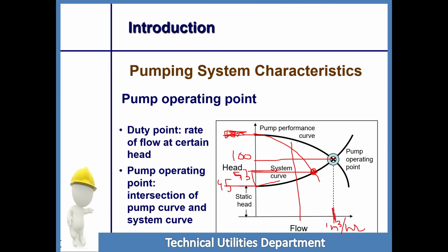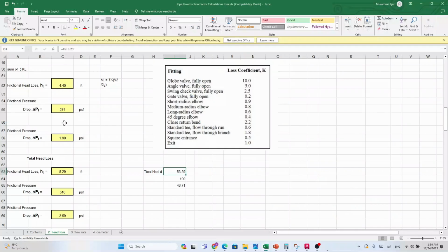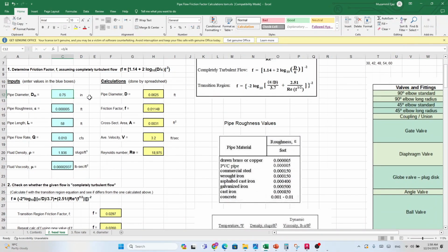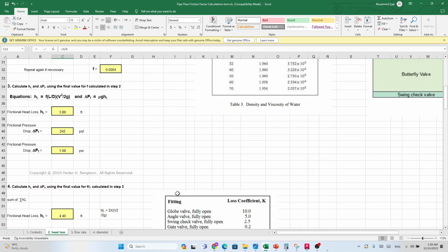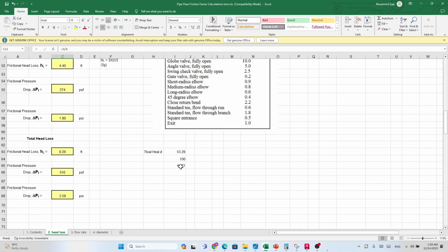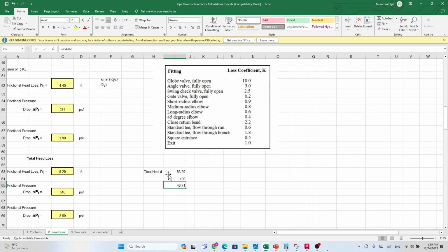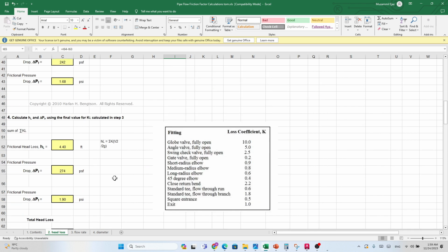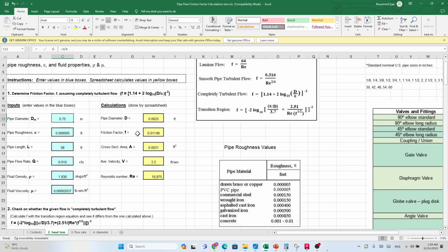So from this you can understand that you can reduce the diameter of the pipe by installing 3 upon 4. You are putting in extra installation cost. You can reduce the diameter because you still have a margin, a lot of margin. You have 46, and you can reduce further loss up to 46 at maximum, but because you need some factor of safety, you cannot put 46; you can make it 40 or 35, and so on. So further reduce the size.